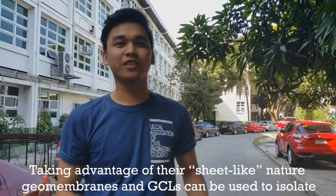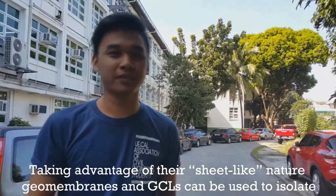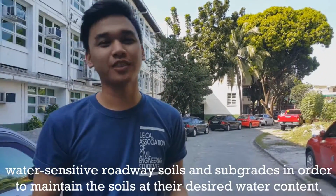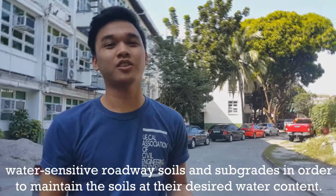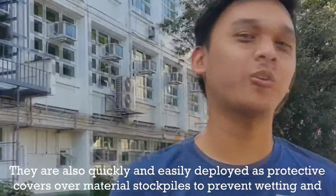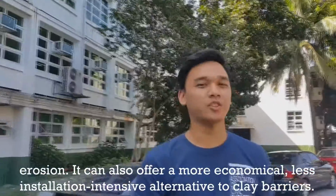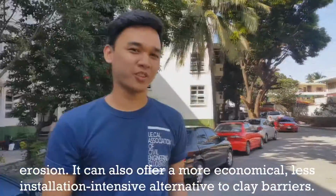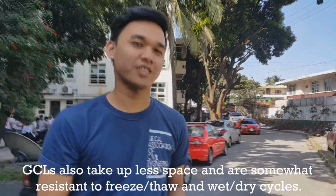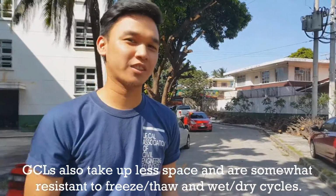Taking advantage of their sheet-like nature, geomembranes and GCLs can be used to isolate water-sensitive roadway soils and subgrades in order to maintain the soils at their desired water content. They are also quickly and easily deployed as protective covers over material stockpiles to prevent wetting and erosion. It can also offer a more economical, less installation-intensive alternative to clay barriers. GCLs also take up less space and are somewhat resistant to freeze-thaw and wet-dry cycles.